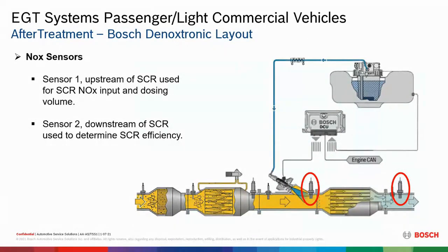Now, the NOx sensors we have in here. Most newer vehicles, probably 19 and up, all have dual sensors in them now. Not all of them, but most of them go into that area. Before that, there was an optional number one sensor. They could do a lot of it with the rear, but most of it, to meet EPA standards to really rectify this thing and know exactly what's going on and get more codes as well,